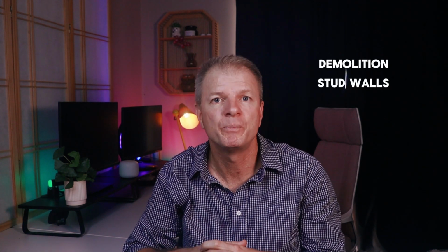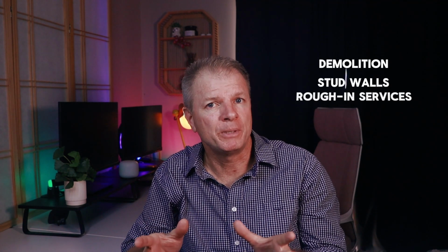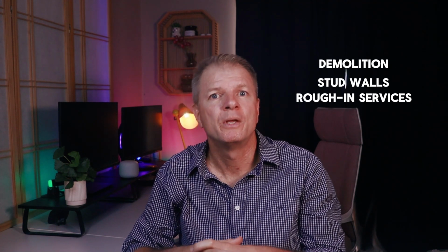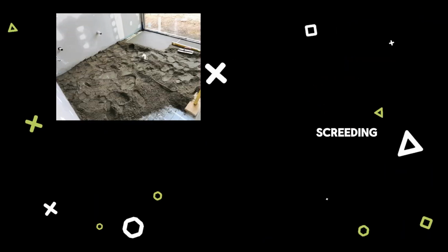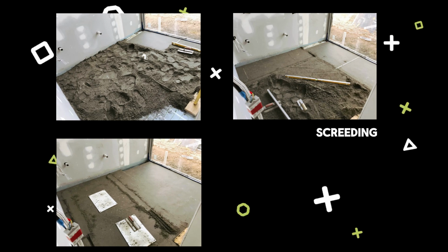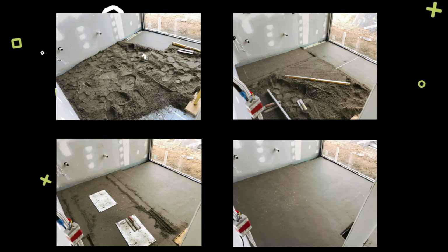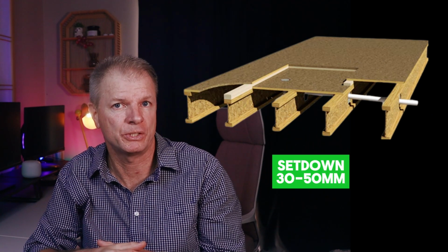Other items or trades captured in the bill of quantities will be demolition and strip out of an existing bathroom if you're remodeling and renovating, stud wall framing to build the new wall, roughing in plumbing, electrical and mechanical, the fibre cement sheeting, screeding. This is a sand and cement mix that is placed carefully to establish the falls in the floor so that water sheds quickly. Screed is usually placed in a set down that is 2 or 3 inches deeper than other floors in the house. Then there's waterproofing, another trade to budget for requiring a primer coat and 2 coats of